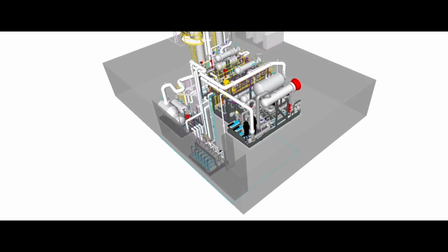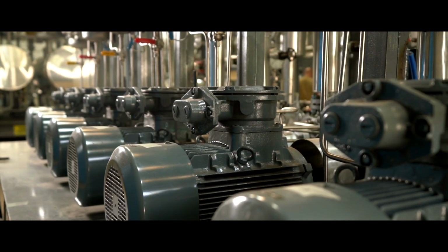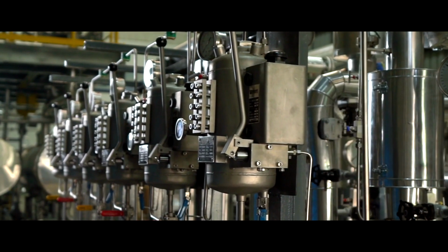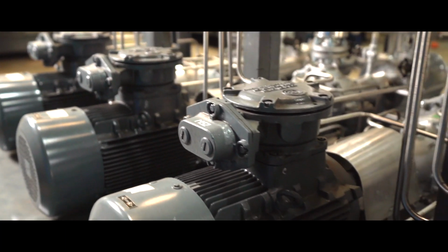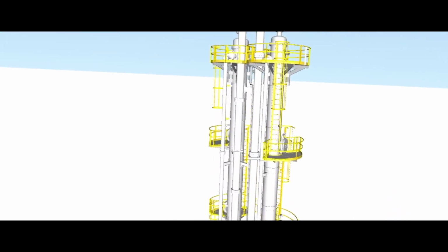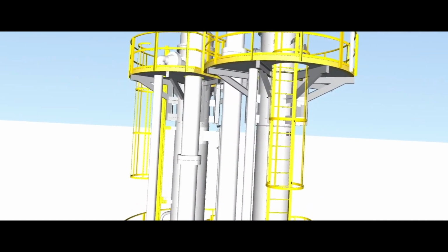The pump skid is located below the ground. It comprises 3 different API 610 hydrocarbon pumps: 1 for pumping product liquid from the bottom of the reboiler, 1 for the overhead liquid, and the third one for reflux. The hot liquid from the OH liquid skid goes to the lead distillation tower as feed. The top overhead vapor then flows to the lag distillation tower.